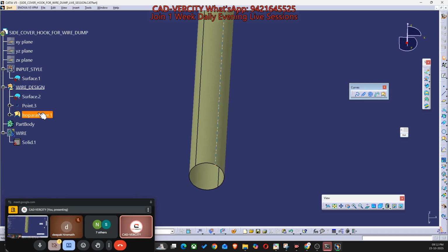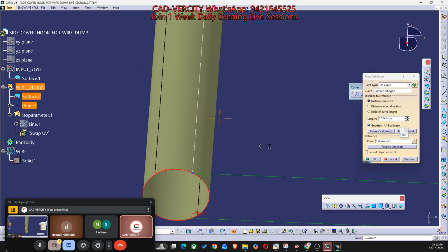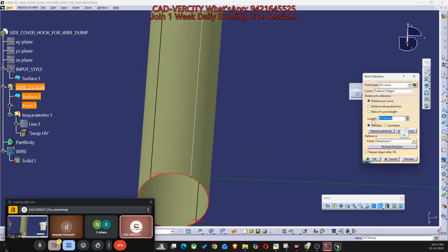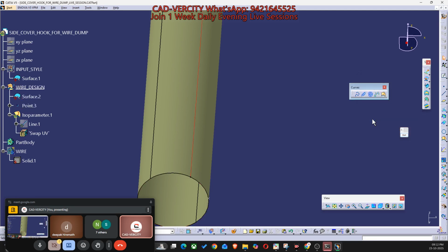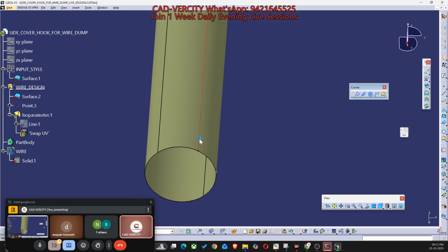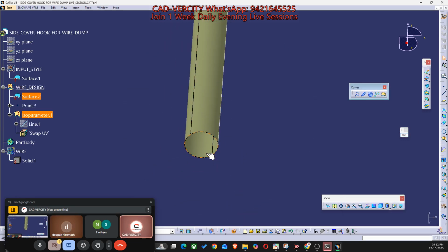So Deepak, this is not a dump curve, okay? It is parametric. If you change the position of this point, the curve will also move. Let's keep, instead of 10 points, let's make it 6. Enter. See, the point is moved now. Right click on the curve, say local update. In my system, if I change anything, it would otherwise update automatically.